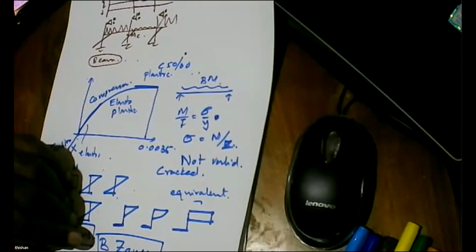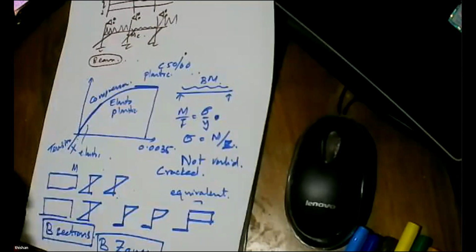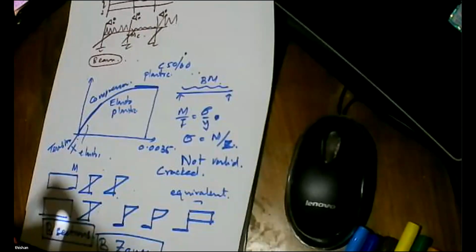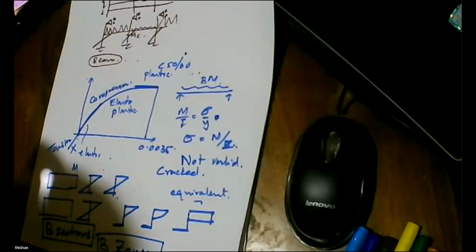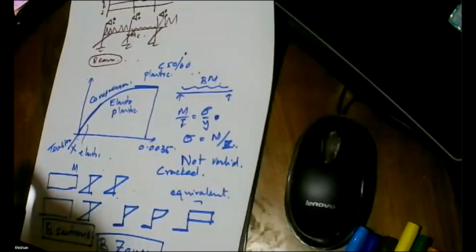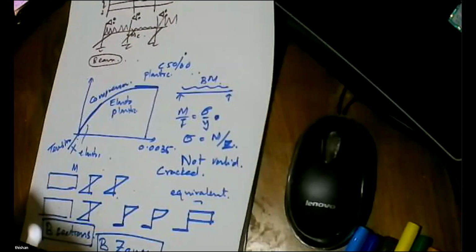on the basis of a soil report, which is a very accurate report. The geotechnical engineer was very correct, giving an end bearing of around 2 to 2.5 newtons per millimeter square. Even when the structural engineer inquired, the geotechnical engineer said no, unfortunately he couldn't give more, because the ultimate compressive strength is low.